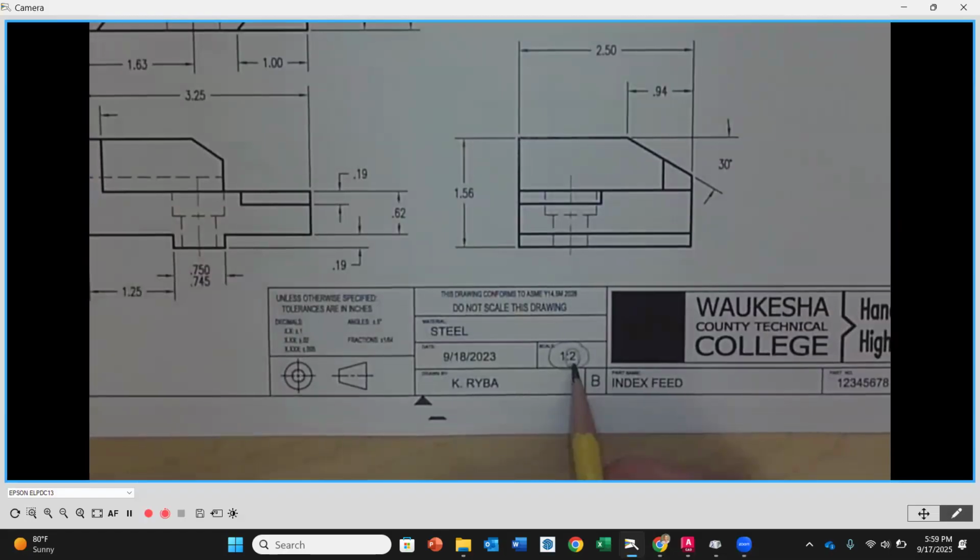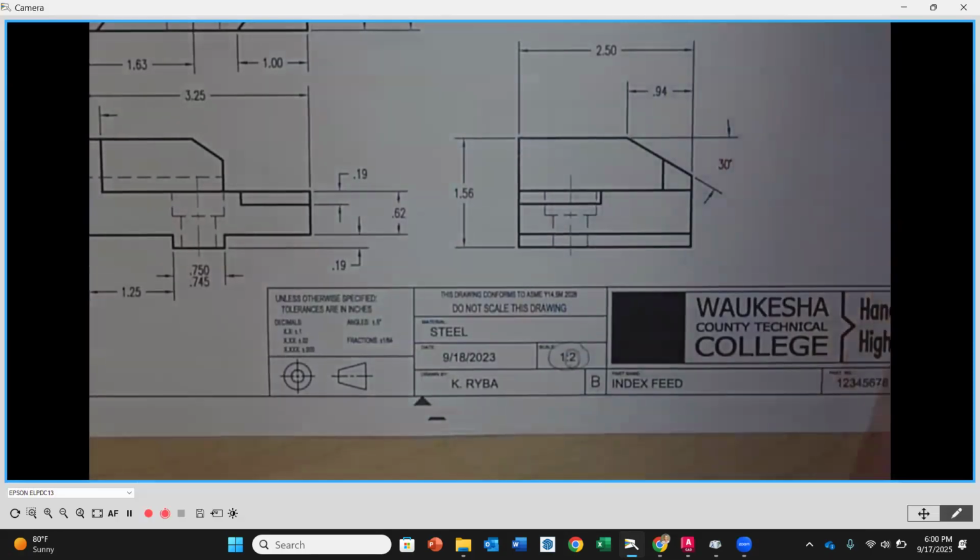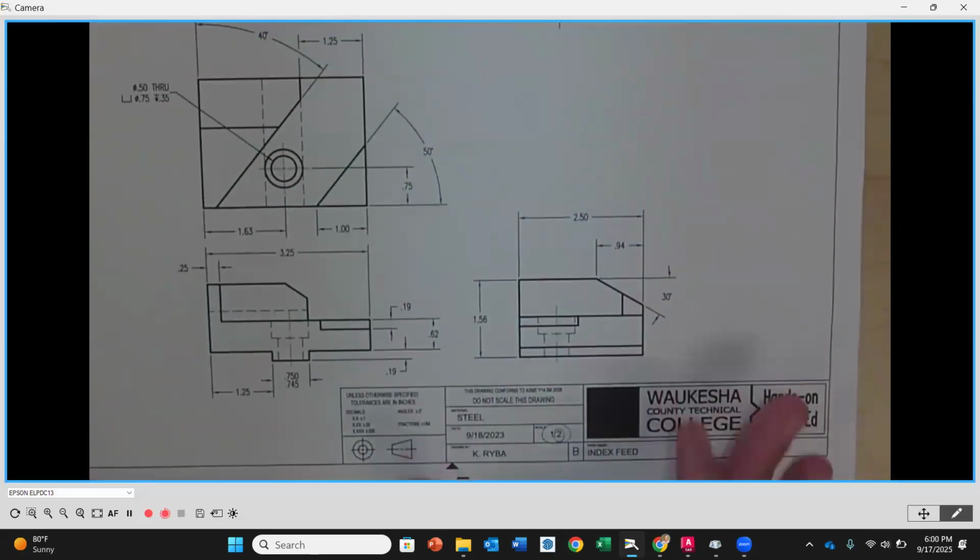So it's always going to be the second number that you're going to pull that in at. If it's 1:1, then you pull it in at 1. Okay. And that means it should fit around. Okay. If it's 1:1.5, then you're pulling it in at 1.5 scale. Okay. And then also know which border you're working with. So what we're going to do now is we're going to pull that border in. It's going to be an insert block from libraries or however that goes.